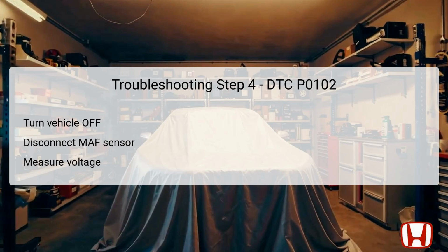The next part of this diagnostic involves turning the ignition to the on position again to measure the voltage at the designated test points between the MAF sensor connector and body ground. This measurement is crucial to determine if there is adequate battery voltage present in the IG1 ACG line. If voltage is detected, it suggests that the wiring from the MAF sensor to the under-fuse relay box is intact, guiding the technician to further steps.